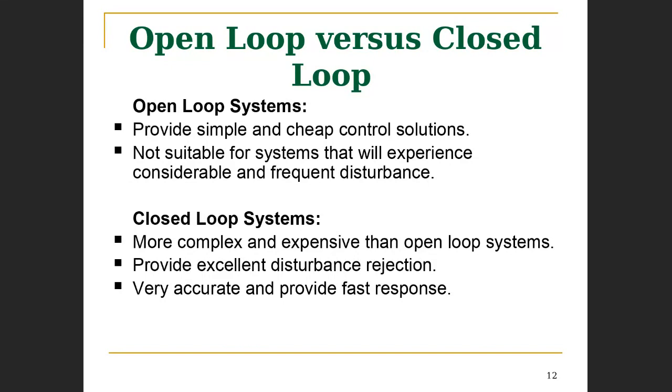All right, so they're not suitable for the control of systems where you have frequent and significant disturbance, and I'll explain that in a little bit. Closed loop systems, now, are more complex than open loop systems, and hence more expensive than the open loop systems. However, they provide excellent disturbance rejection, and they provide very accurate and fast response to disturbance.